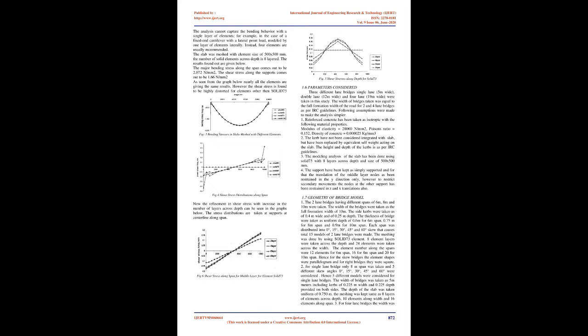At each node the element has 6 degrees of freedom and translations in the nodal x, y, and z directions and rotations about the nodal x, y, and z axes. Stress stiffening and large deflection capabilities are included. A consistent tangent stiffness matrix option is available for use in large deflection, finite rotation analyses. SOLID 186 is a higher order 3D 20-node structural solid element. It has quadratic displacement behavior and is well suited to modeling irregular meshes.